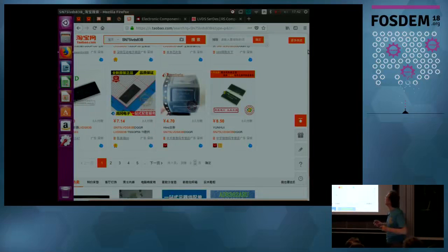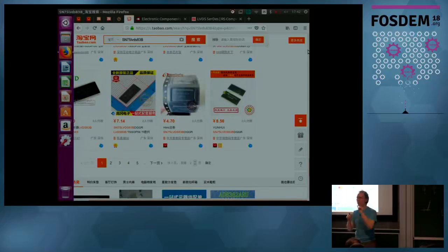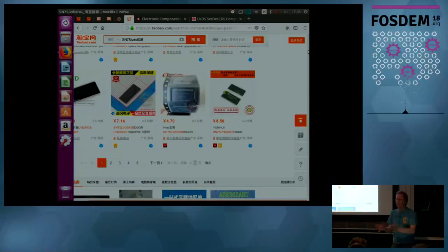But it's this information that I'm giving you here that is completely missing. So, step 1: look on DigiKey, find the datasheet, check that it suits your needs. Step 2: before you design the PCB and the schematic with the part, check the availability using either AliExpress or Taobao, to check the quantity of suppliers and the diversity of suppliers. And if it's not available, don't use it. I'm really serious. Do not use that part. Find an equivalent circuit that uses an alternative part.